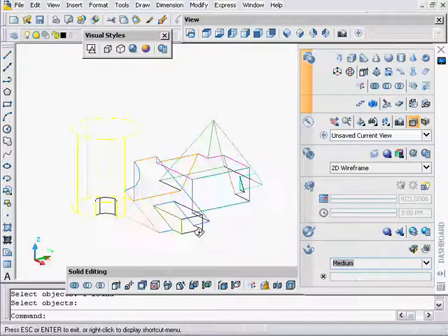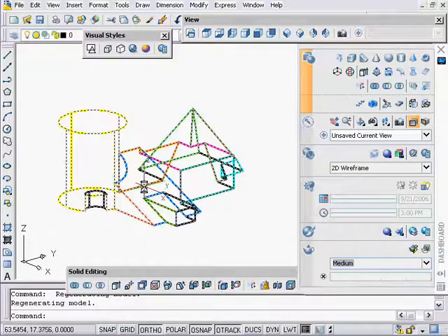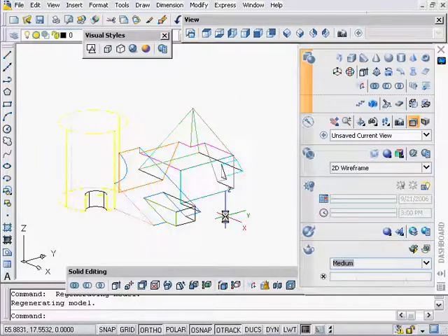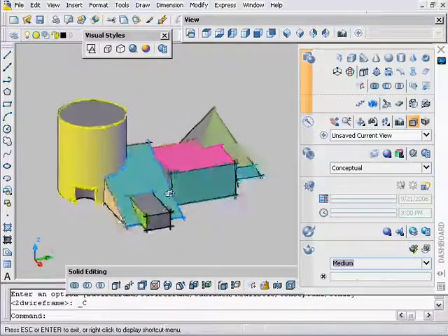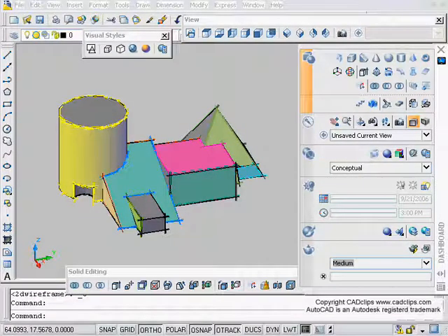So they can be placed in plan, in elevation, in section, in a 3D view. All your settings, right click on it, have a look at the options, right click everything every time, wherever you get a chance to, and then use your grips as well to manage your section planes.